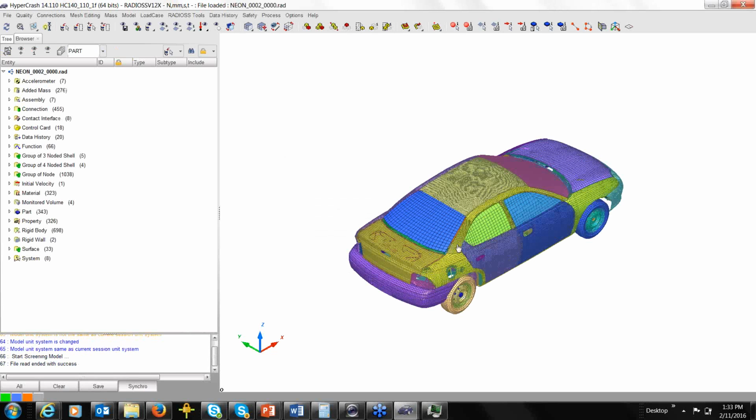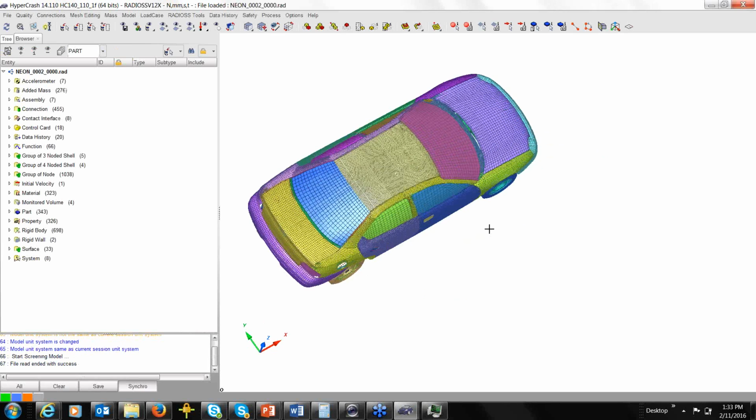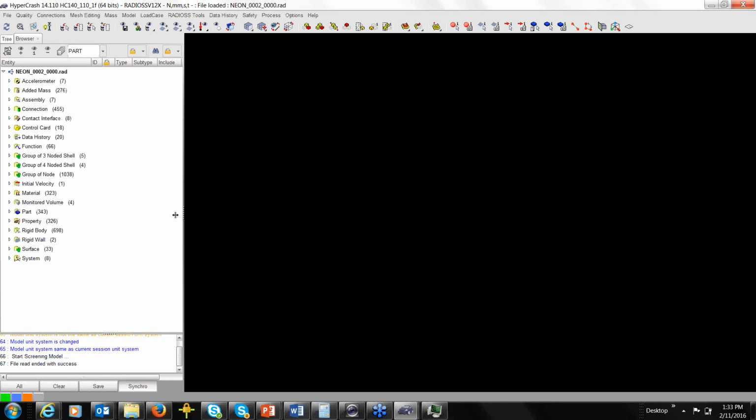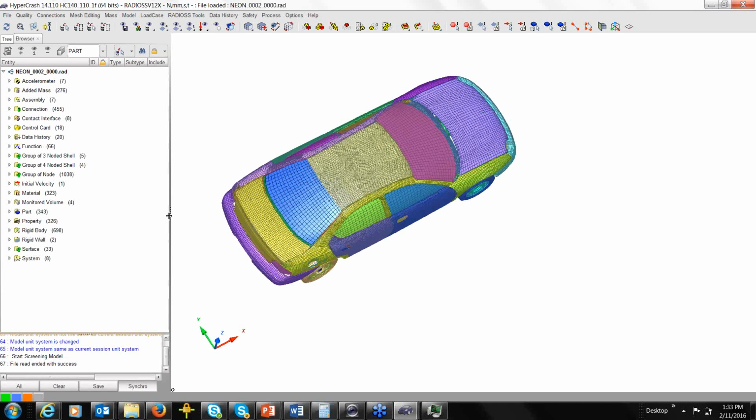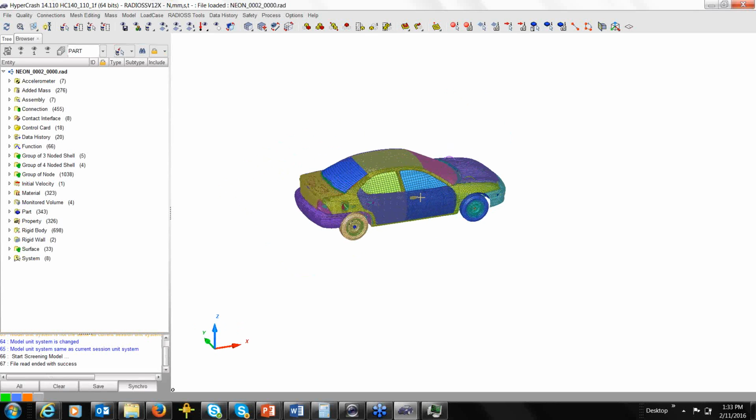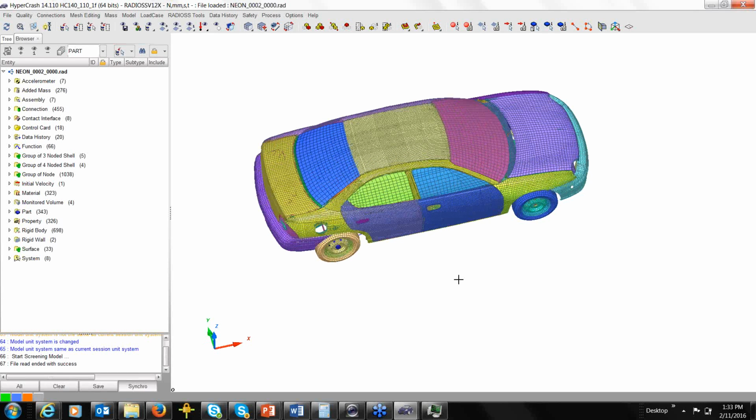It's not just building the model, but after you finish building the model, before you run the job, I want to emphasize this. As a support engineer or application engineer, I work in the field a lot, and I see many people finish building their model in the preprocessor, HyperMesh, or HyperGraph, and then they submit the job. They don't even check the input. It's a bad habit. You have to check the quality of the model because you can't guarantee everything you've done is right.